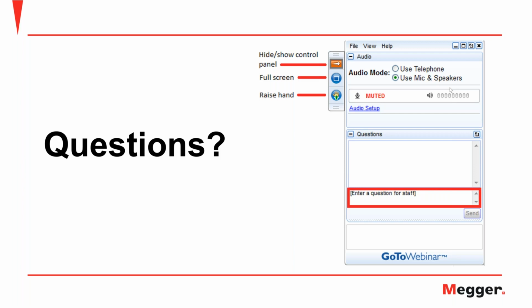Then the other point is, what about interference with your test result? Well, again, the tester is looking for its own frequency, so it should be okay. So you definitely do not have to shut down the substation in order to do a test, and they do it all the time, and it's just industry standard procedure.